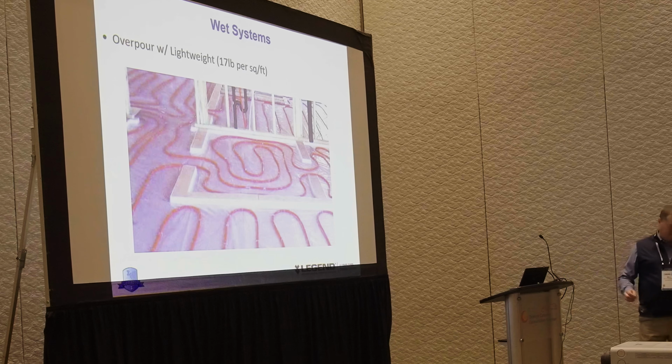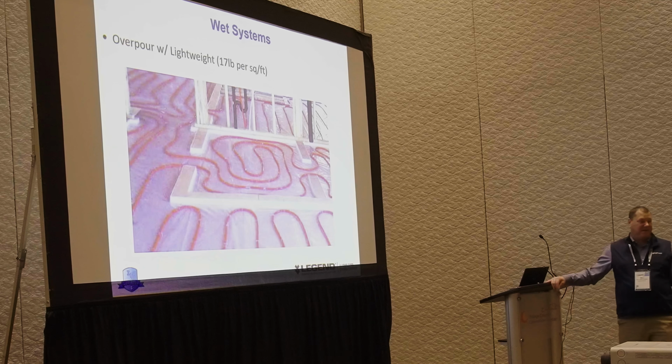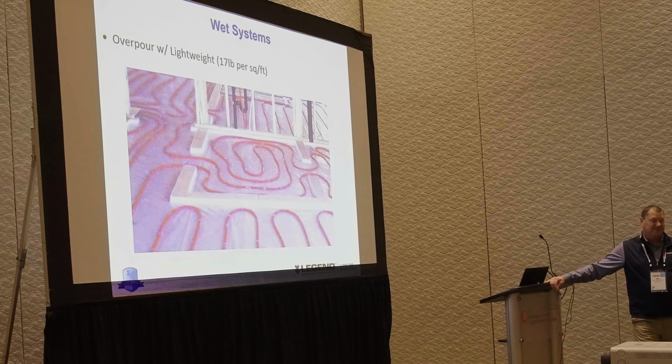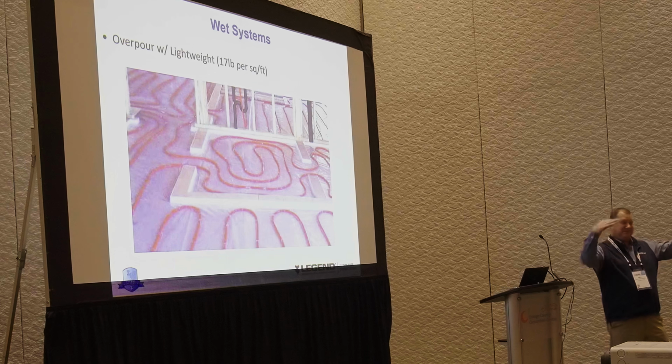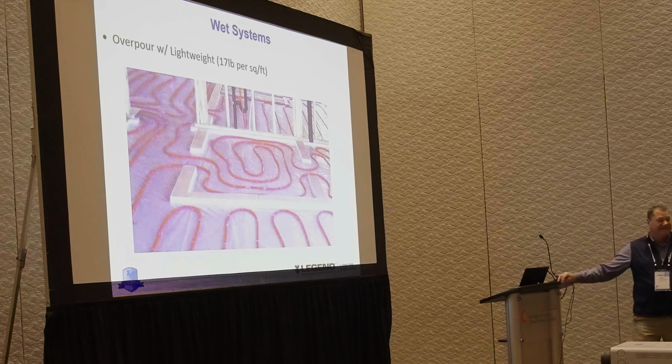But the water weight in the concrete, you have to figure that in. It's not just the weight of the concrete, it's the weight of the concrete plus the water. Yes. I've seen a project where they dumped a bunch of concrete onto a second floor, and they point loaded it while they were doing it, and it just, whoa, I thought it was gonna be a bad failure.